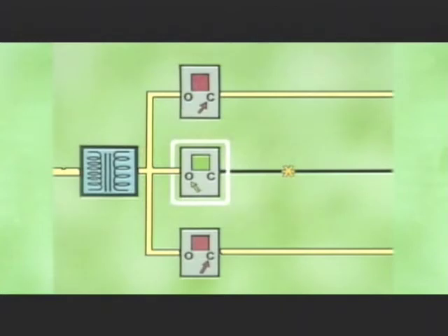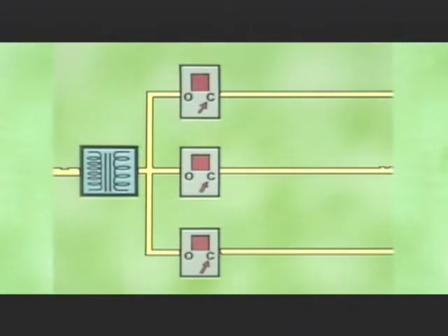In general, circuit breakers are designed to open and then close automatically after a specific period of time has elapsed. If the fault is temporary, as in the case of a tree branch swaying into a feeder, it usually clears fairly quickly. When the circuit breaker closes, service is restored, and the system continues to operate normally.